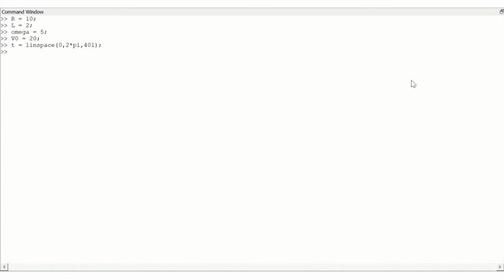Now we can start to calculate the impedance. We know that in this case, since R and L are in a series circuit, the complex impedance is given by R plus i omega L. And this is how I put it into Octave. You have a complex, and then you put in the x and y components of the complex number, which is R, and on the other hand omega times L.